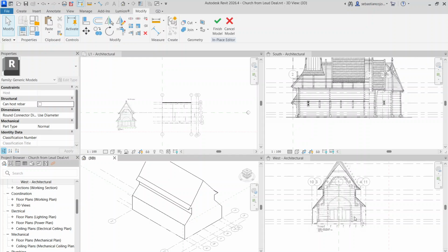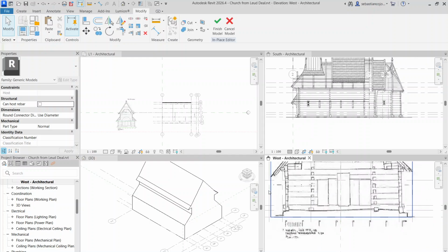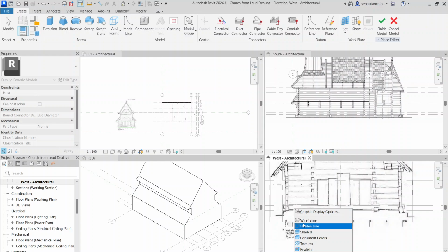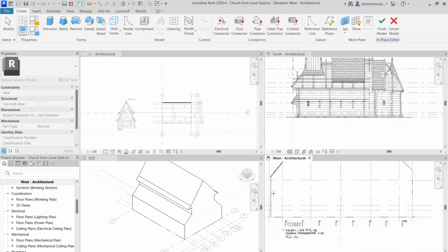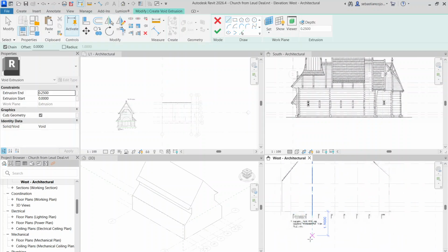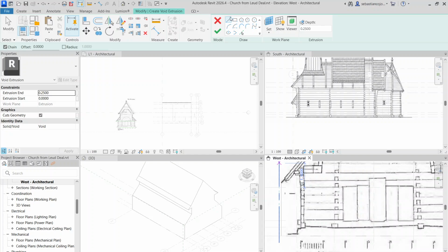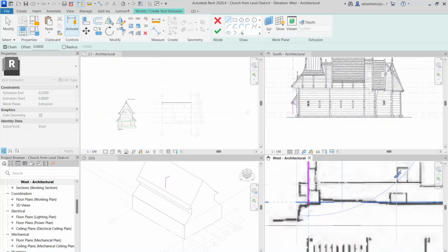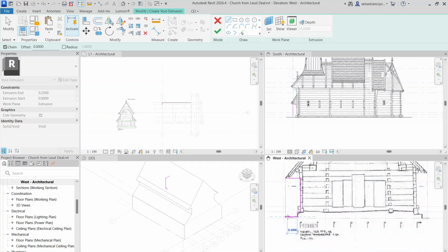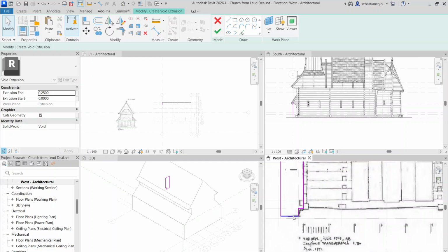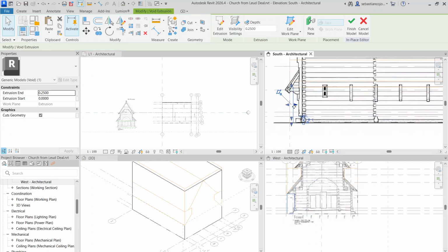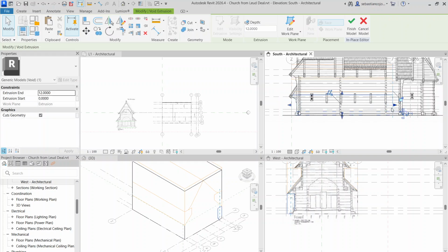Okay. Let's see what else do we have. We have another profile to make. So create, void forms, void extrusion, pick a plane, set it hidden line. It will reset the pick plane. I set my plane, keep it wireframe, draw it once again. Great. Take into account this, let's say, stepping. Okay. Let's say I have it defined. Great. Click, drag by the arrow.